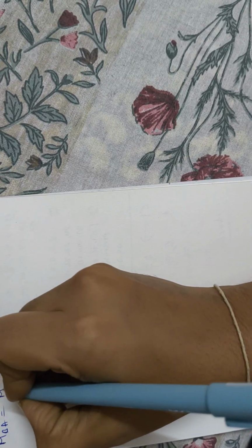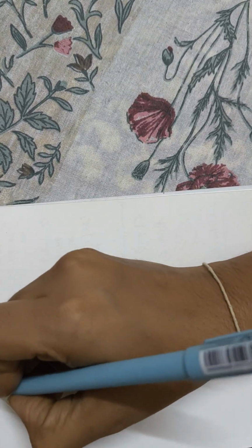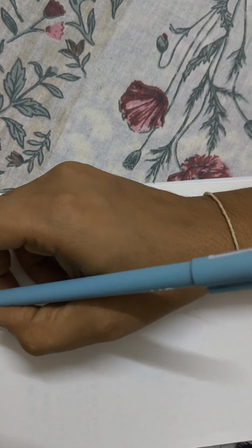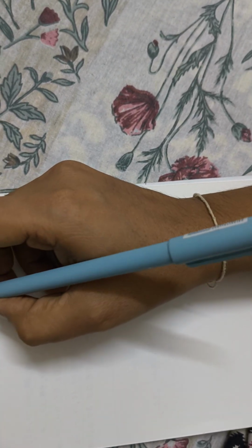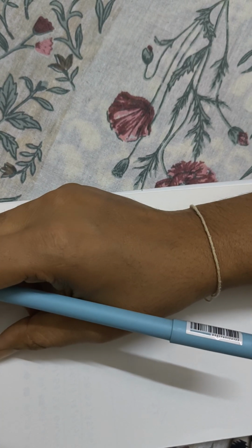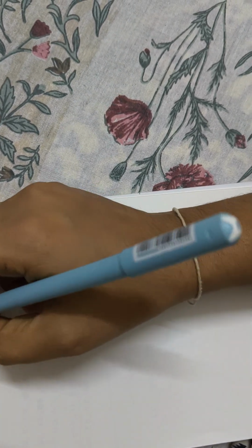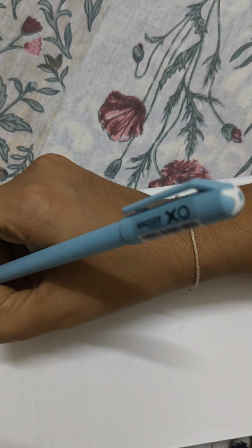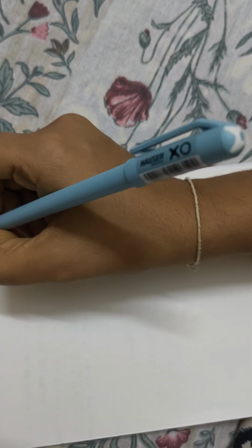MBA equals M bar BA, because it is also a fixed end moment, so use the general formula only. Where there is a hinge support, you must apply the modified equation, but here it is a fixed support, so that's why I'm using the general formula: 2 times theta b plus theta a minus 3 times delta by L.